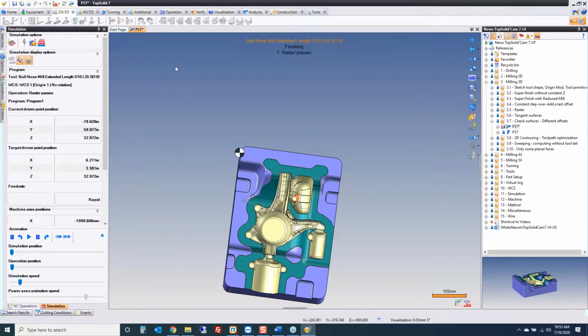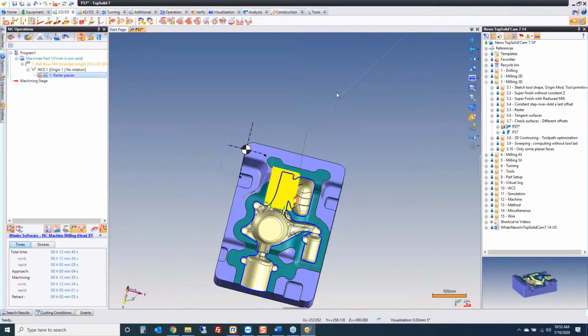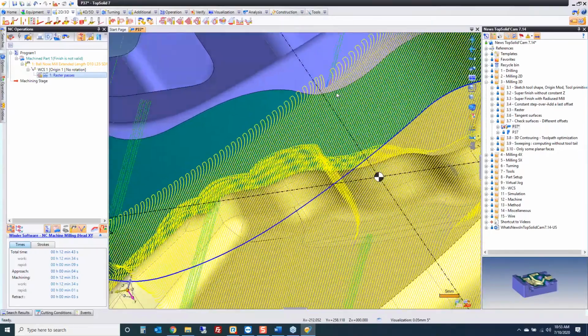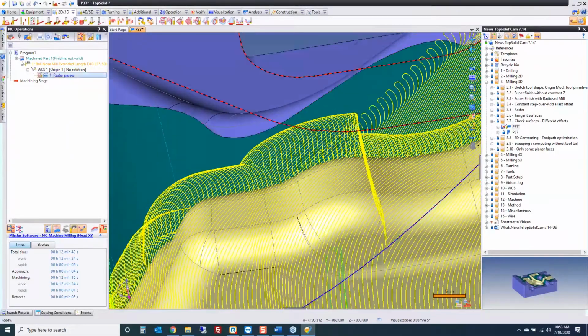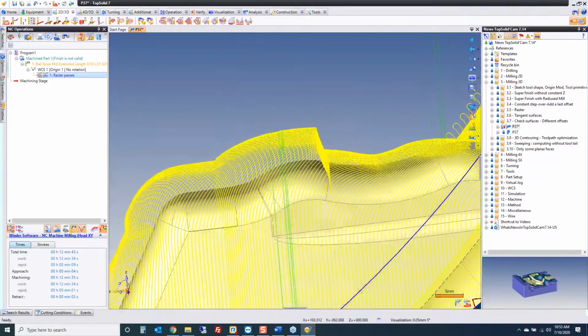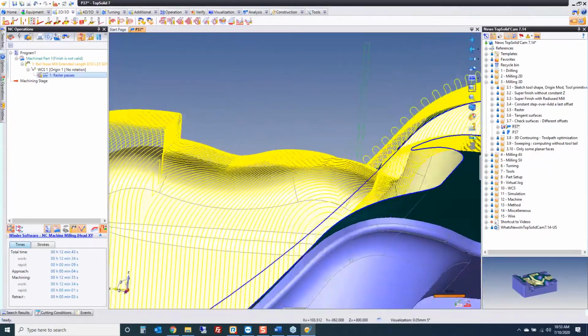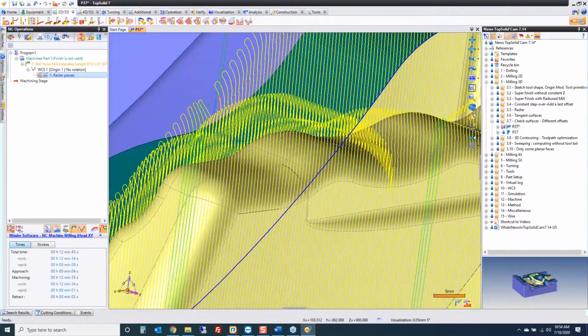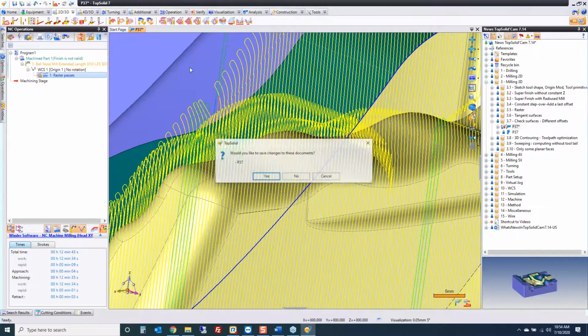And then here we'll have a look at the resulting toolpath. So we'll zoom way up here, and you can see how the offsets are affecting the toolpath. Where this might be useful is if you have a shutoff on a mold and you want to semi-finish that shutoff but finish everything surrounding it, then you can apply a simple little offset like this and keep on machining with nice smooth toolpath motion.